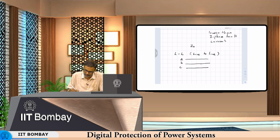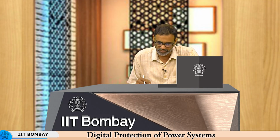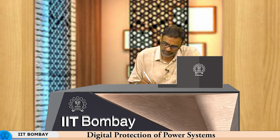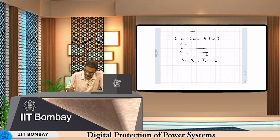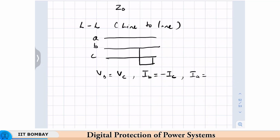We will take that there is a solid fault between phases B and C, since we are talking of line to line, which means two phases are shorted. Just for the ease of analysis, we are taking B and C. It could be A and B or A and C as well. Since there is a solid short between B and C, we have VB equal to VC, and since the current is the same, IB is equal to minus IC, or IC is equal to minus IB, whichever way you choose. And since the pre-fault load currents are 0, IA is equal to 0.